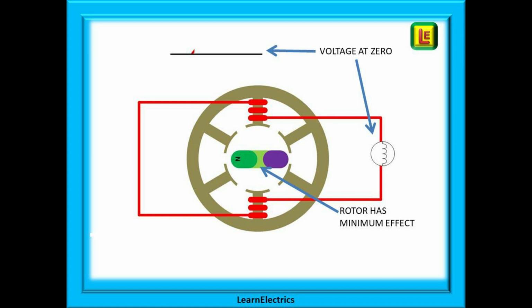This is a very simplified explanation of single phase generation. The rotor in this drawing is going to spin at 50 cycles per second. It is made of a powerful magnet with a north and south magnetic pole. It starts here at a central position between two coils on the stator. We use the word rotor for the rotating part and the word stator for the stationary part.